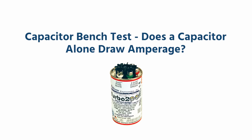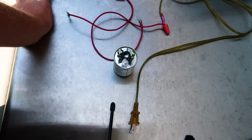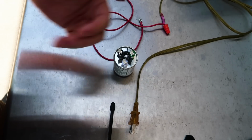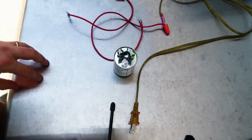All right, so let's do another quick demonstration. A lot of technicians know that this is a run capacitor, right? Something real quick, there's no relay in this. This is constantly in the circuit when it has voltage applied to it, when it has potential applied to it. A lot of confusion between a start capacitor, which has a potential relay that takes it out of the circuit, and a run capacitor, which constantly stays in series with the start winding of a motor, okay? So this stays in the circuit all the time.